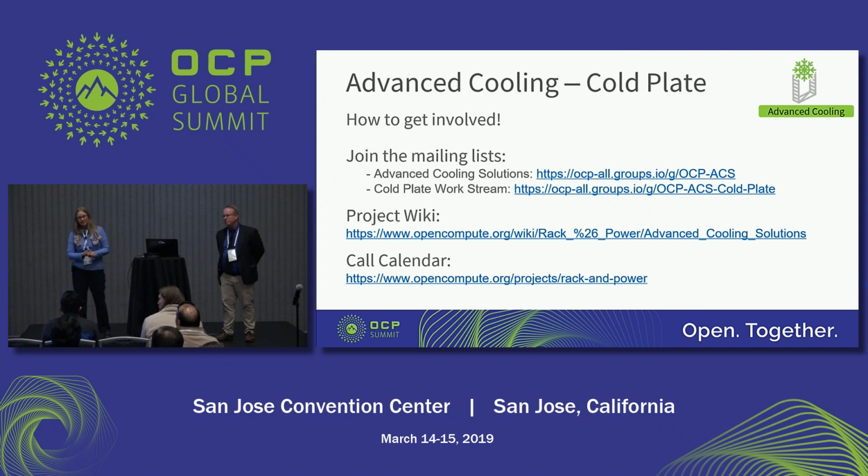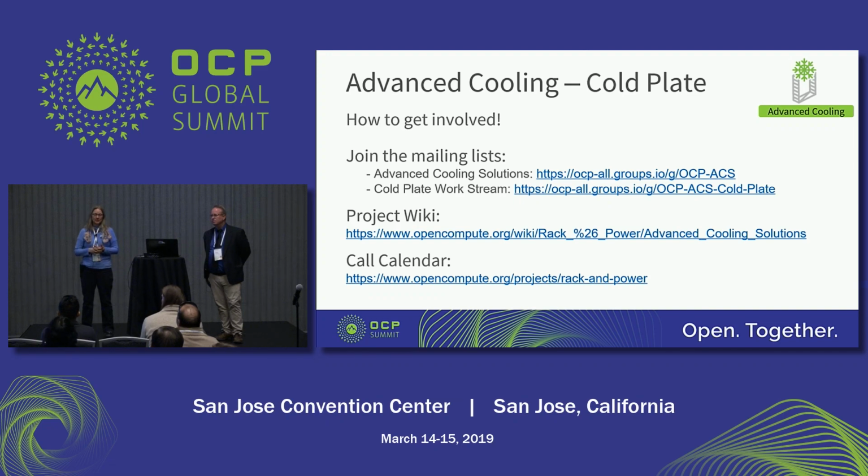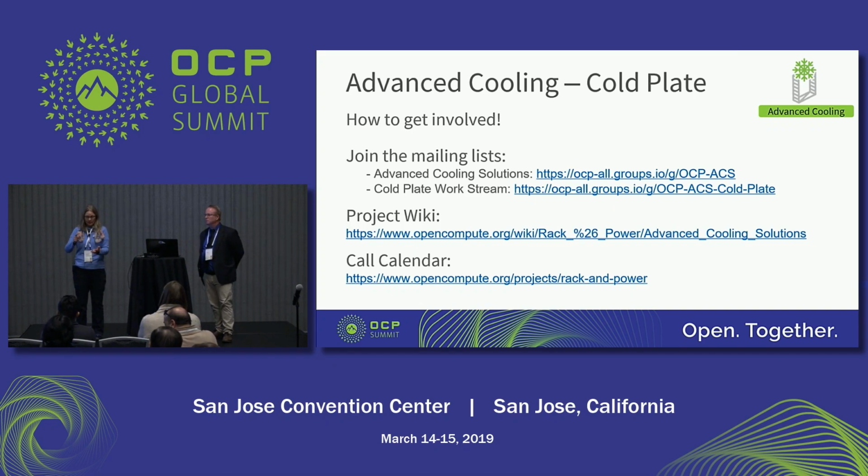Did you use a dielectric fluid? We have not. No, we selected a propylene glycol fluid, and that's the one that we have been testing with. But I should say, from the cold plate workstream perspective, I'm not saying that there will only be one solution. As I was mentioning, there are different fluids that can be used: water-based, glycol-based, or dielectric.